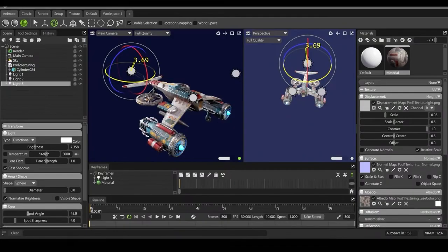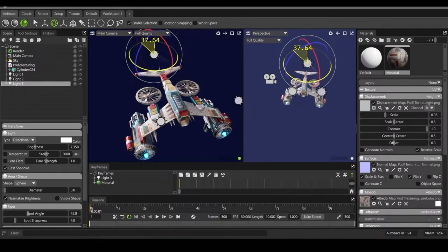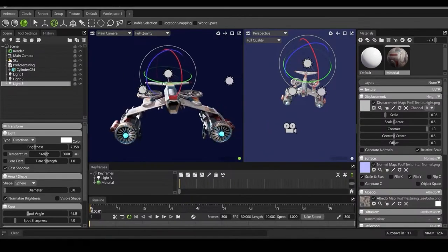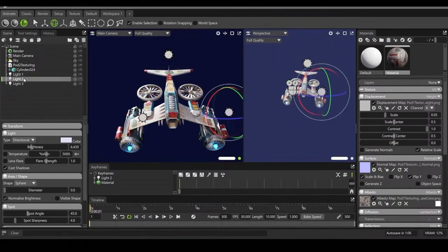As I'm adjusting each light, I'm constantly rotating around the model. Different angles reveal different reflections, and sometimes moving a light just a few degrees creates much nicer highlights across the surface. Don't just look at one camera angle. Orbit around the model and make sure the lighting works from multiple viewpoints. That's especially important if you're creating portfolio images or turntable animations.